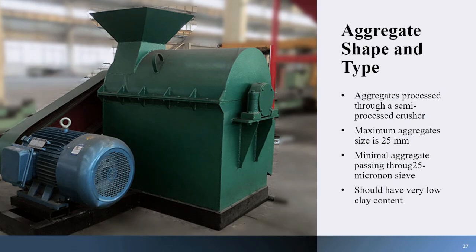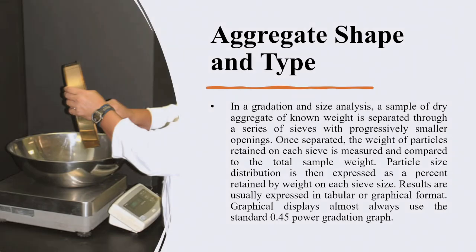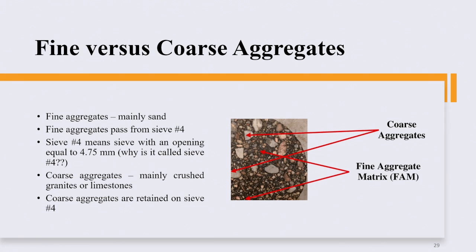Other than that, the strength of the aggregate and the maximum size of the aggregate are other important factors. As I said, 25 millimeter is used in a lot of applications. We go up to even 30 millimeter if we are talking about stone matrix for fighting ruts.